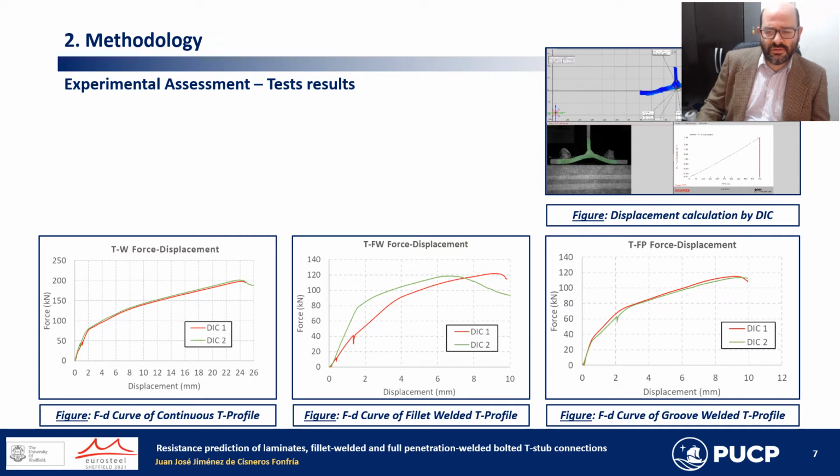In results, characteristic force displacement relationships of ductile connections were observed. For the first stage, a linear elastic behavior is observed. As the load increased, the bolt and the flange start yielding, so begin to reduce the stiffness until the rupture of some of the elements, the bolt or the fracture in the welding too.